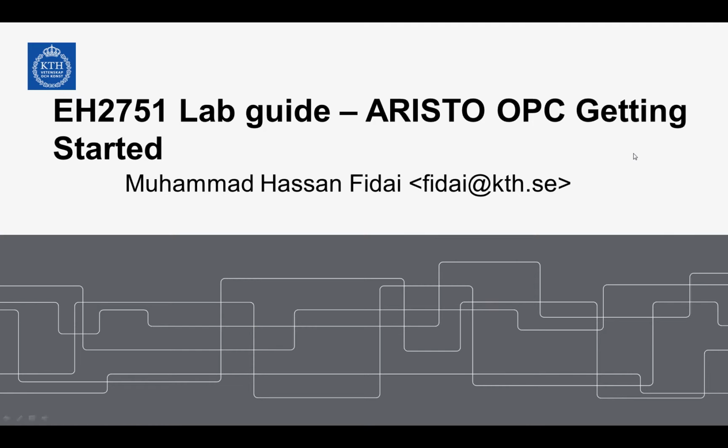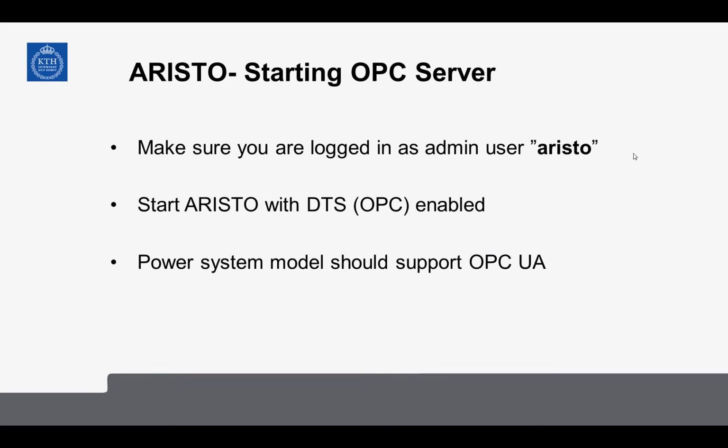Hi everyone. In this short video, I am going to guide you how to get started with this OPC functionality in ARISTO. First, make sure that when you log into ARISTO, you are logged in as an admin user named ARISTO, because this is the only user in which OPC works.